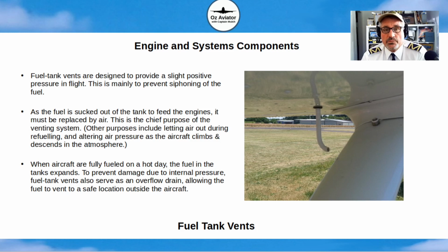One last reason also is on a hot day, especially if you've really filled your fuel tanks up high, as the temperature increases, your fuel will expand and it needs somewhere to be able to get out of the fuel tank, and the fuel tank vent will allow some overflow.